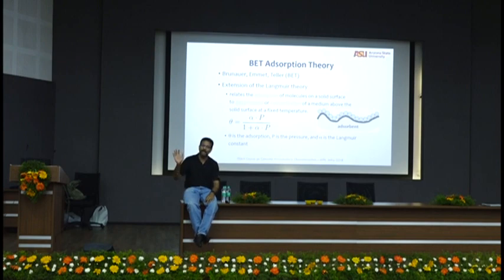and you apply a pressure and find out when you don't have to apply any more pressure, you know nitrogen has completely covered the surfaces. You know how much pressure you applied, you know the quantity of nitrogen you sent, and you back-calculate the surface area. Right? Because at the end of the day, surface area is what dictates durability. If you have more surface area of cement paste available for deleterious materials to react, you have more problems, right? So surface area characterization becomes very important. So is the idea clear?